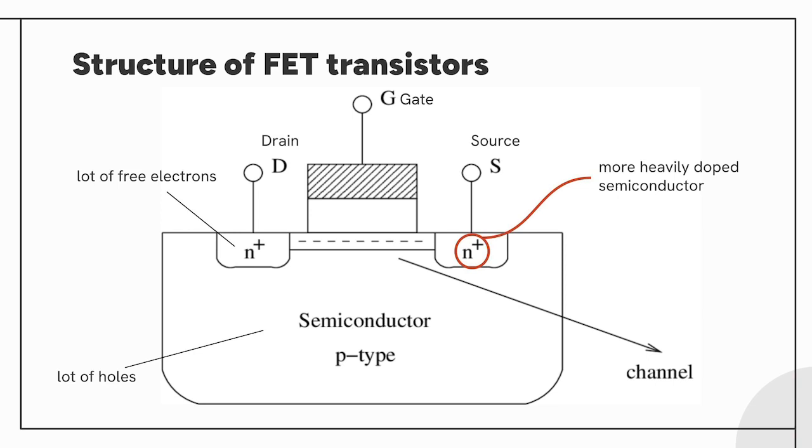This is called an accumulation state, and in this case, the current cannot flow between the N-type semiconductors. Simply put, the holes are accumulated in a small space, so even if the electrons try to go over, they merge with the holes and disappear, so the electrons can't go over.